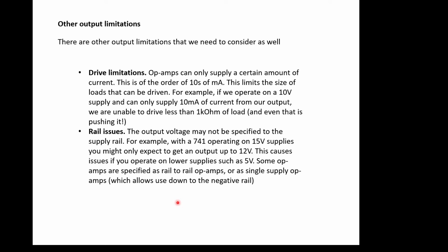Right, so there are other output limitations, drive limitations. Op amps can only supply a certain amount of current, and this is usually very low, tens of milliamps or so, which limits the size of a load that can be driven. You can't drive things that are expecting large amounts of current, so you can't drive very low impedance loads. So, for example, if you operate on a 10 volt supply and your op amp can only supply 10 milliamps of current at the output, you can't drive less than a kilo ohm of load, so 100 ohms would be no good. And even this will be starting to load the output.